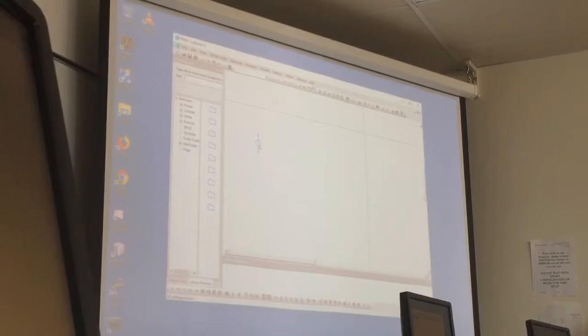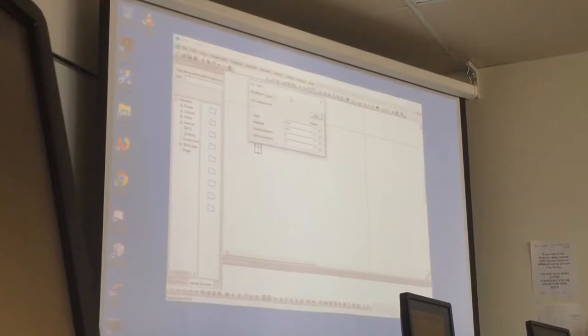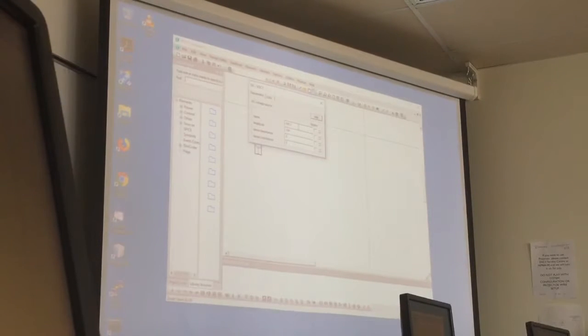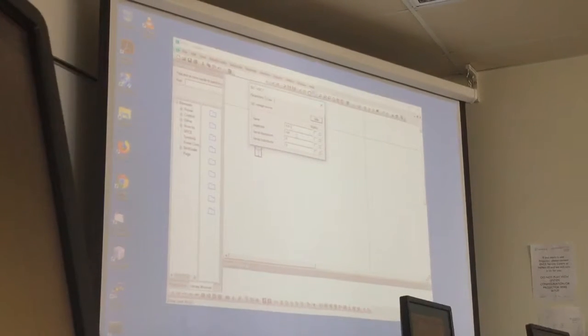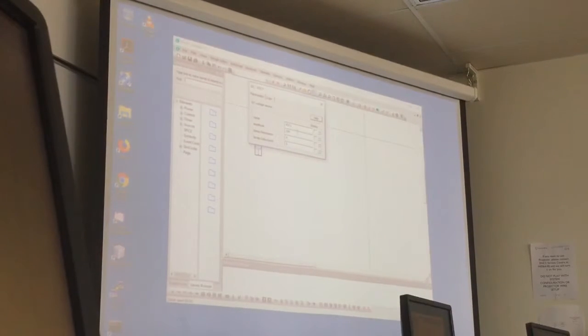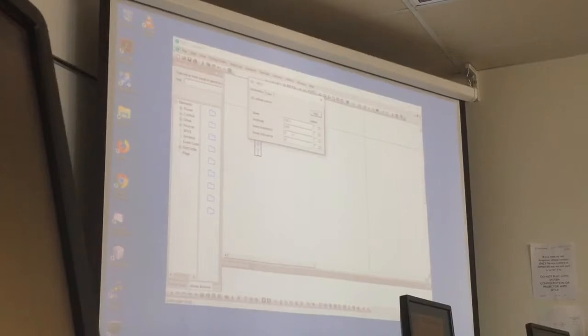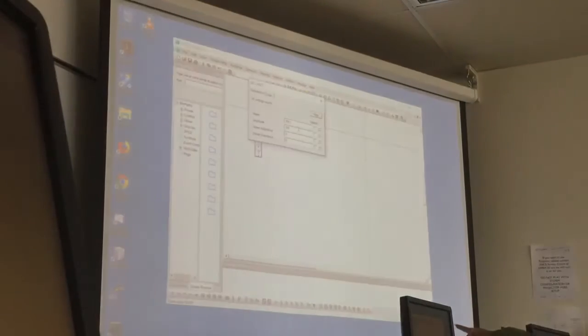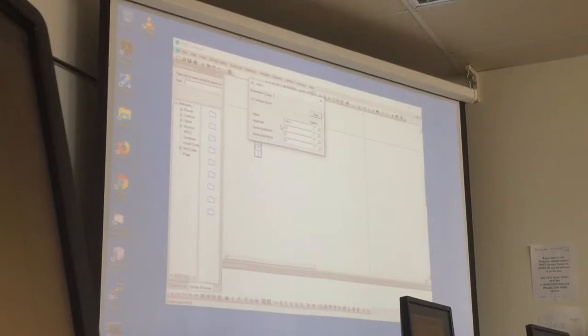When you double click on the element, you can change these parameters. You can change the name, which is not important at all, but you can change the value of the voltage. You can have a series resistance or a series inductance. Right now it's better, for the series resistance and these kinds of elements, to keep it at 0, so you're going to have an ideal element. But let's imagine now that we have a 48 DC bus. Okay, 48. We have 48 volts here.